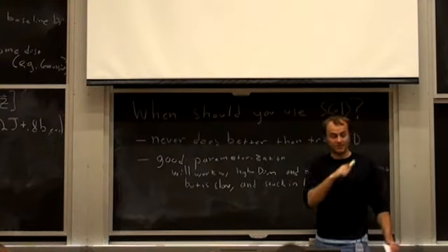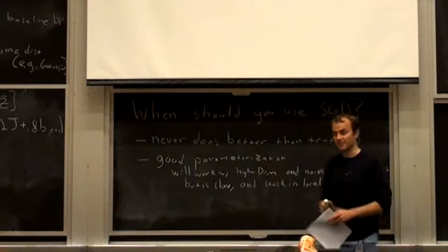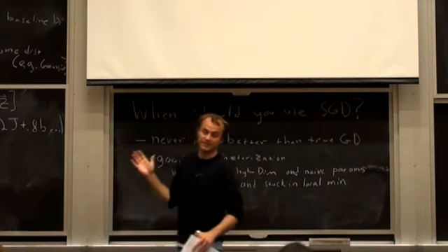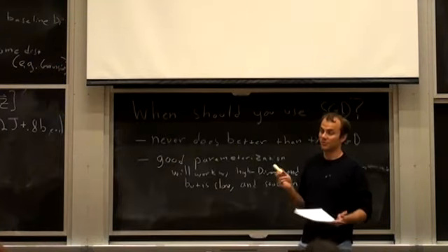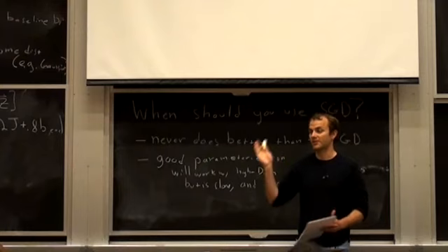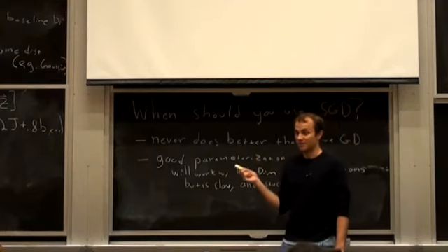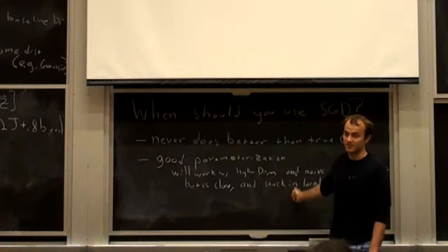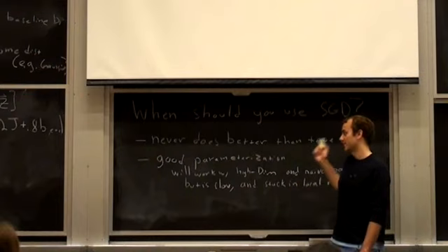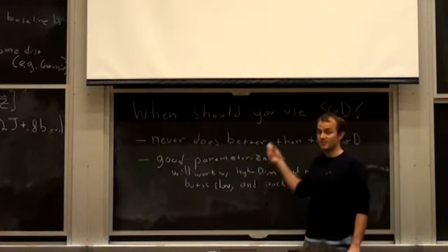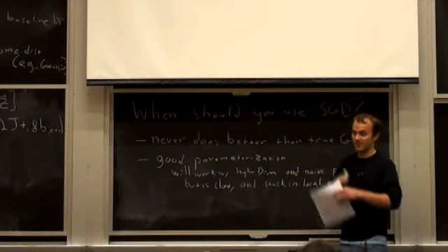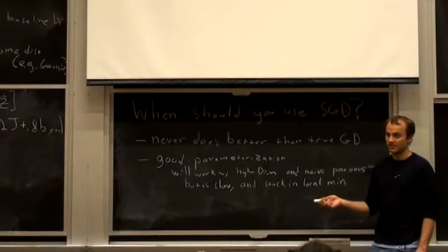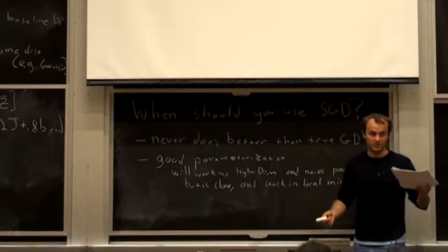An example is in our lab, we have this glider. They're trying to have it perch. So we launch out of this catapult. It flies through, executes a maneuver, and then tries to catch this line. Now, in that case, if your parameterization were the kind of open loop tapes we've previously used, where it's just what elevator angle do you try to servo to, that could be a bad parameterization. It's very coarse. It's going to demand rough things. And so trying to do learning on that could be very slow, especially because an evaluation is so expensive. So if we can come up with a good parameterization, it suddenly becomes reasonable to do this. If we can knock down to 5 parameters that parameterize a very nice class of policies, now maybe we don't need that much data, and we can actually get it just by launching it. So if we can come up with that good parameterization, doing this should work.